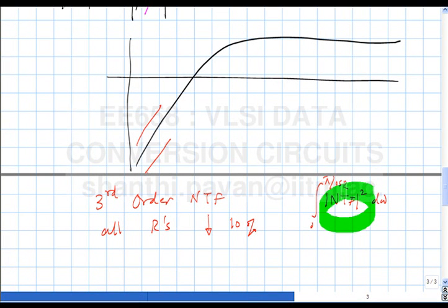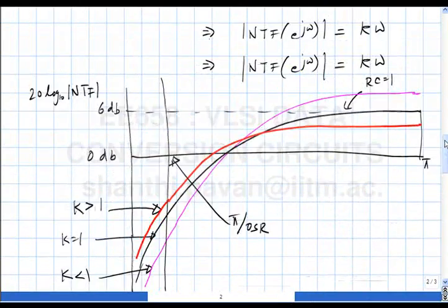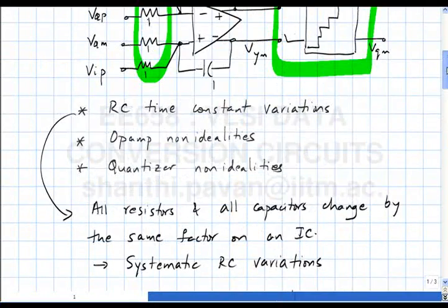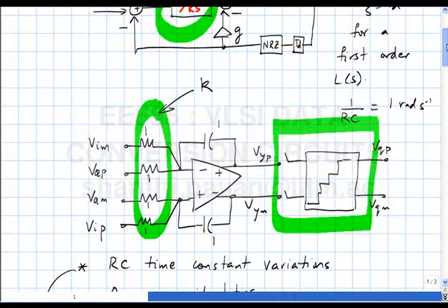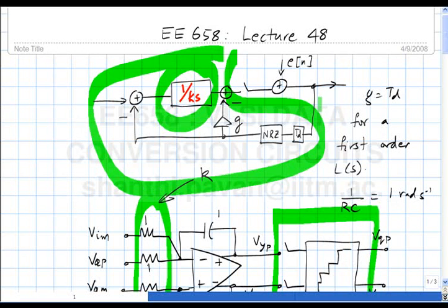We said the area below the dB line is the same as above, only for a discrete filter. No. Please note that this whole Bode sensitivity stuff is only valid for a discrete time system, as we discussed. But if I look at it like this, I am applying a discrete impulse here and what I get here is also a discrete impulse.